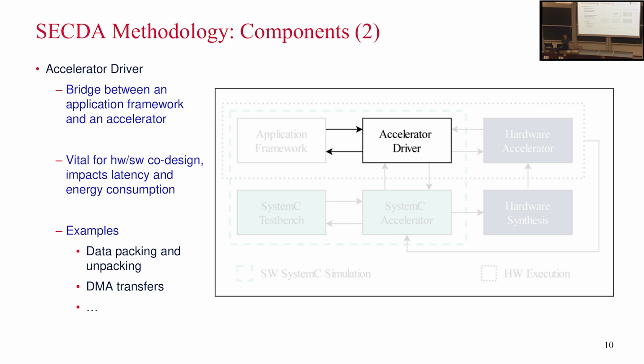The driver, as you can imagine, is an essential component because it manages the communication and the interaction with the accelerator itself. So here is where we are doing part of the hardware-software co-design, right? We co-design the hardware, the data packing, and the DMA transfer that we do with the hardware. So it's important to be aware of what the real hardware is offering: how many processing elements, how big the buffers are, and the memory.